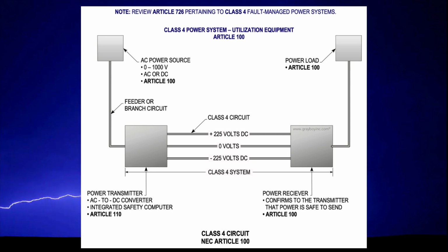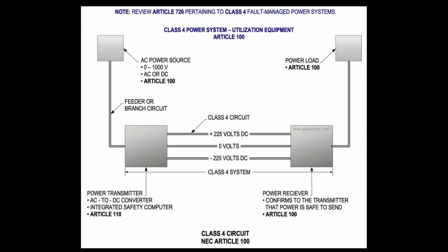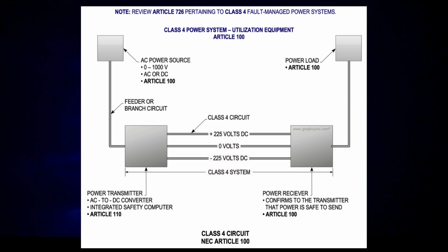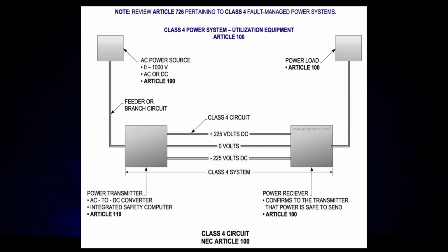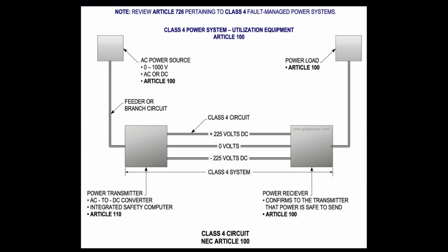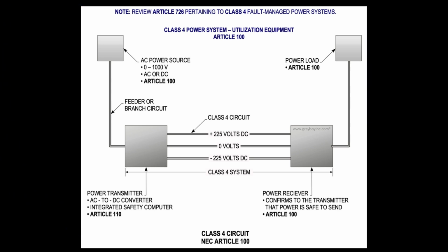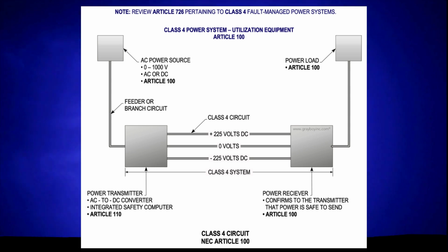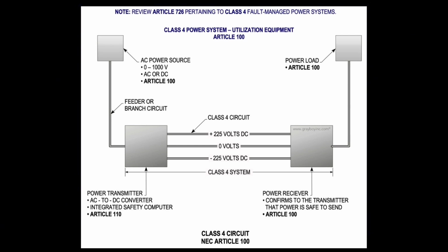Unlike Class 2 circuits, which place finite limits for sinusoidal AC and DC voltages to reduce the risk of electric shock, Class 4 circuits need to consider voltage levels, pulse widths, repetitive pulses, time to shut off, and stored charge from cable capacitance and equipment. This is not something an installer, or an AHJ, can do in the field. There will have to be a reliance on the safety standards and the listing of equipment.